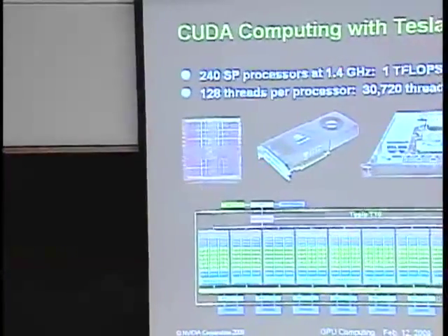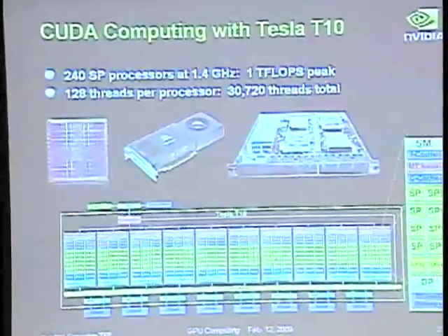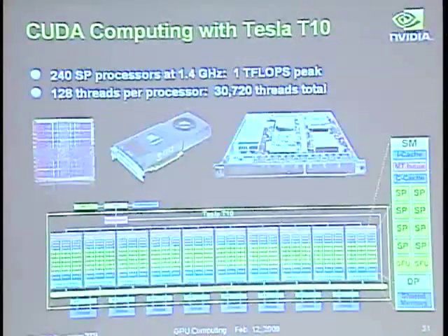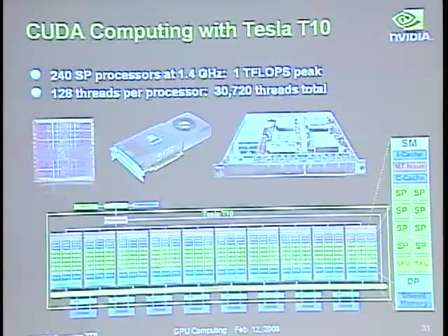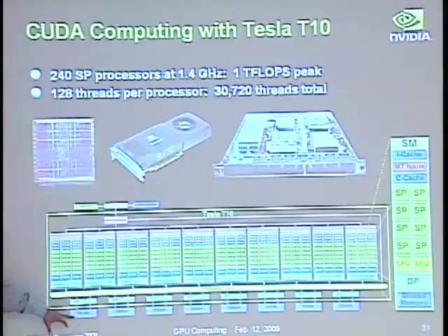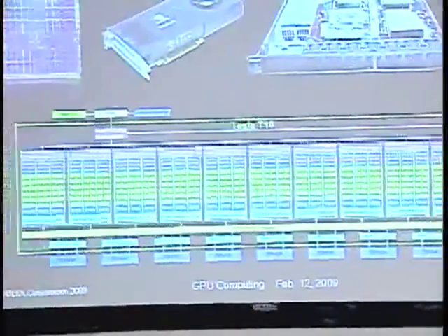Are textures also stored in global memory, or are CUDA textures stored in a separate, faster area? Well, okay. Global memory is just a way to describe the DRAM, and textures are stored there too. So if you look in the DRAM, there's a mixture of textures and render targets and load store data and program instructions and stack space, all that kind of stuff.